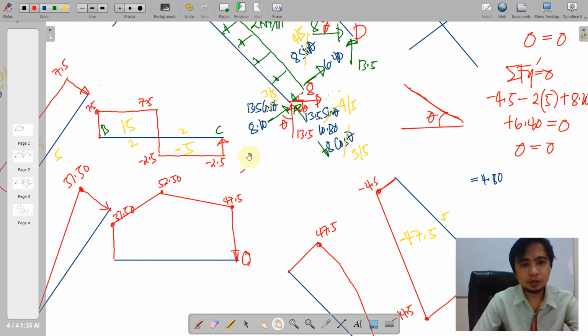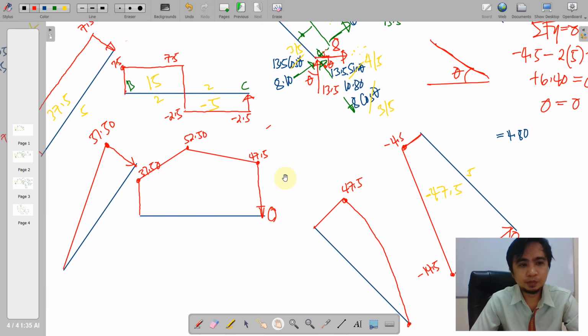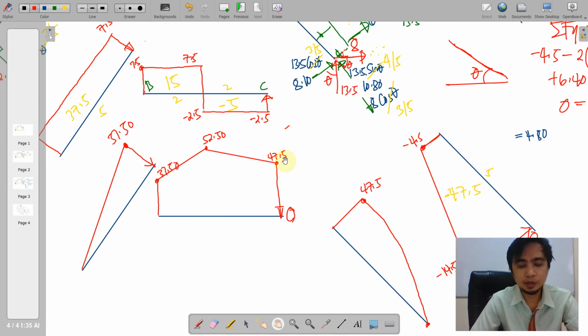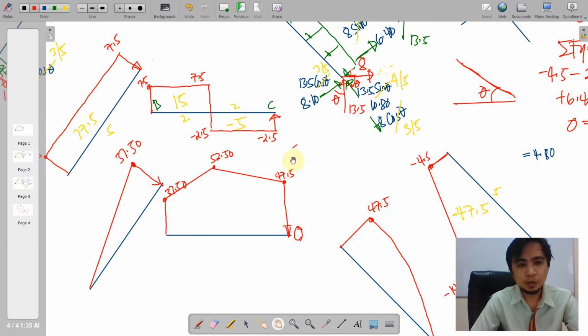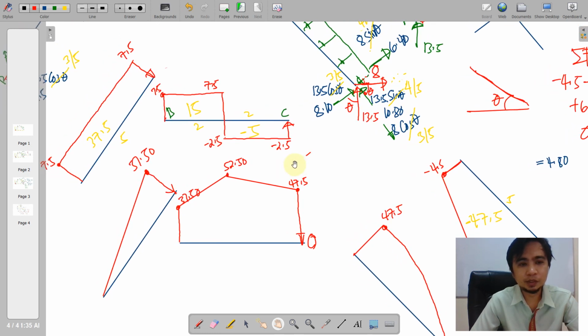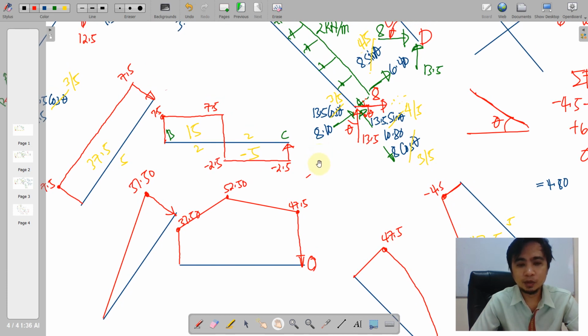Okay, again, let us have more practice at home to sharpen our knowledge. So it is just but normal that along the way we commit errors, but errors could be checked by some parts of our solution, like if your shear diagram does not close to 0, or your reaction is not satisfying the equilibrium equation.